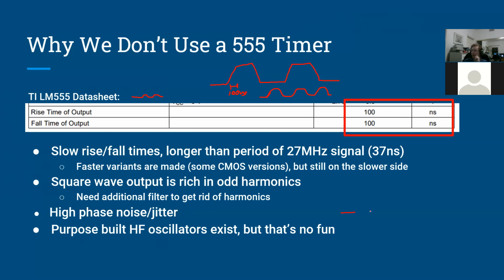So if you imagine a frequency plot, you'd want your oscillator to look like this, where this is frequency. But what really happens is these tails in the spectrum appear, and that's called phase noise. And that's very undesirable in wireless communications or communications in general, as well as for digital circuits. So it's not isolated to just communications.